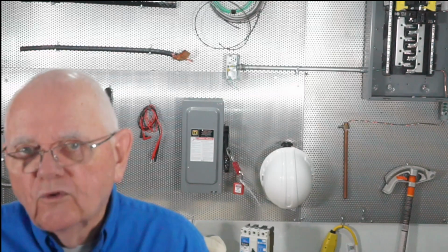And then the last thing I want to mention is individual room air conditioners. And that's in Part 7 of Article 440. And it tells us what a room air conditioner is that we're talking about. It's all a self-contained unit, isn't it? It has the hermetic compressor in there, the coils, the condenser coils on the back side, and so on and so forth, and the controls are with it. It's all one contained unit. And we probably mount it typically in a window, maybe in a hole in the wall, whatever.